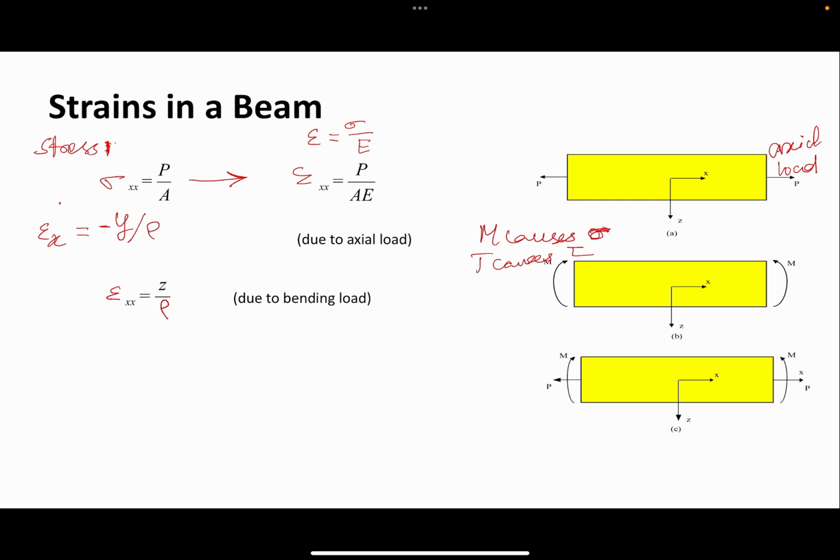And if you forgot what rho was, I'll show you. One of the major assumptions we make in the bending calculation is that our beam, if it's subject to rotation, however it bends, this way or the opposite way, always bends in the form of a smooth circular arc, which means it's part of a circle with the center somewhere at C, and the radius is called the radius of curvature.